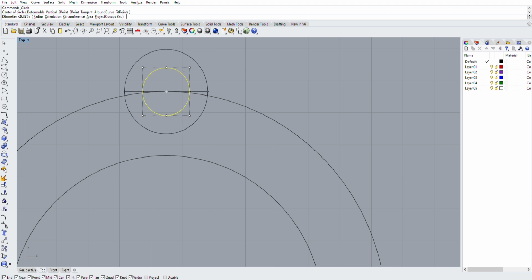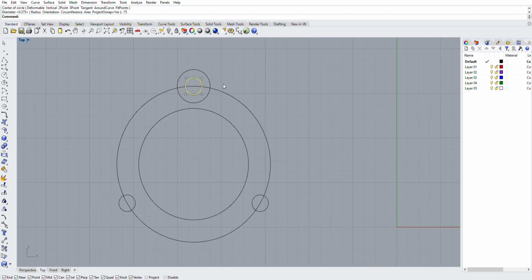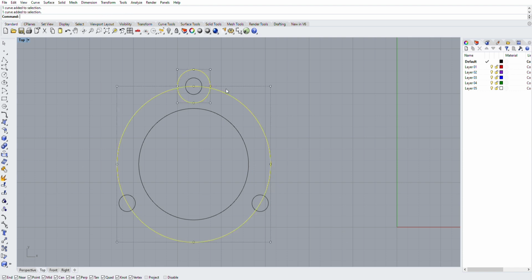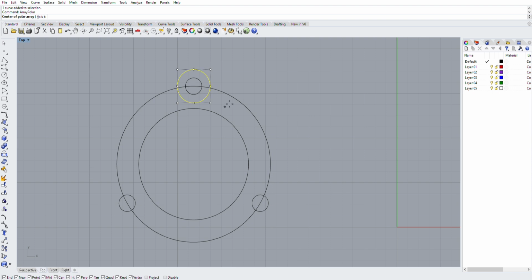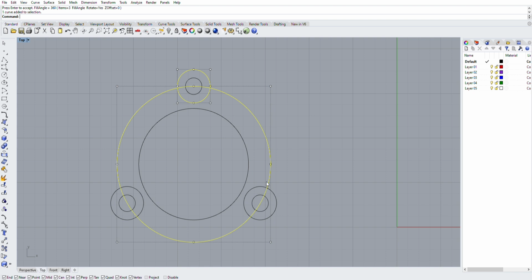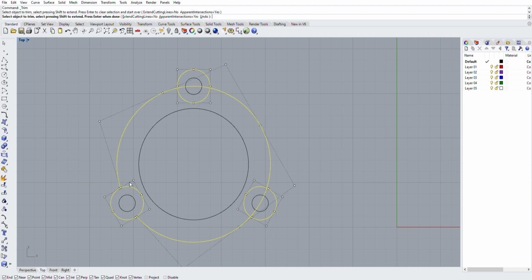If we did this 5 on 4.5, you could make a 1/4 inch wheel spacer just that easily. On a 1/4 inch wheel spacer, you set your center hole, you set your outer size, and you set your bolt pattern holes. There's no trimming, no nothing. It's an inner circle and outer circle and 5 holes in the middle of it, and you could make a wheel spacer. Now, all of this is the exact same as what we just did on the other flange. The difference being we based our bolt pattern off a 3 on 3.5 bolt pattern.